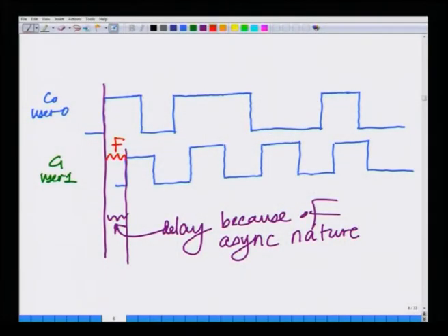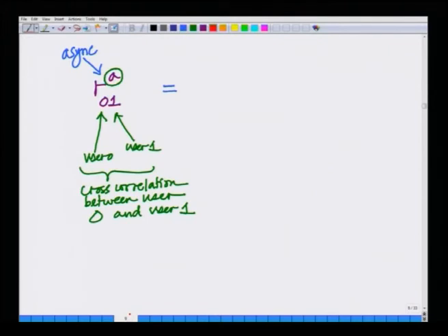So, as the fraction f varies between 0 and 1 to different degrees of extent, when I correlate C0 and C1, part of C0 is correlated with the shifted C1 and part of C0, the code of user 0, is correlated with the direct C1, because look at this, when we directly multiply these two, this part here multiplies with the shifted sequence, while this part here multiplies with what we had previously.